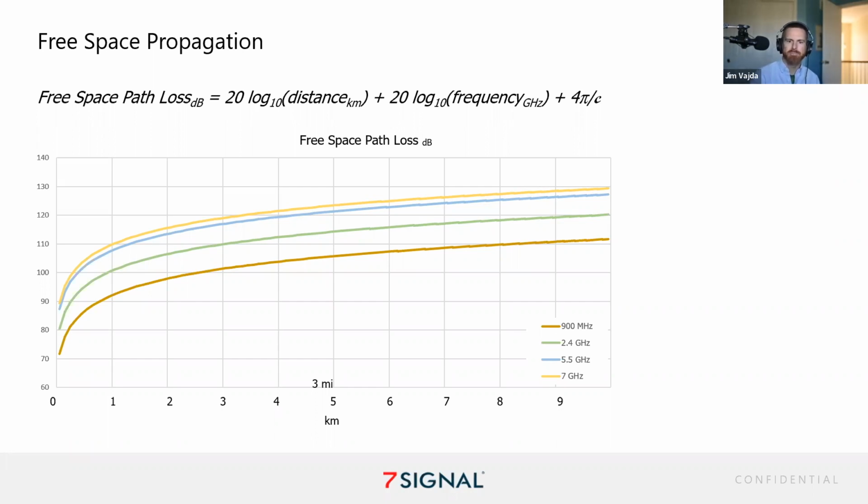So the antenna, at higher frequencies, will absorb less and less power, and that's just a function of the frequency itself. All things equal, you will get about 6 dB lower signal between 5 gigahertz and 2.4 just because of that. Now, there's a lot of techniques to make up for that, particularly with those very high frequencies.